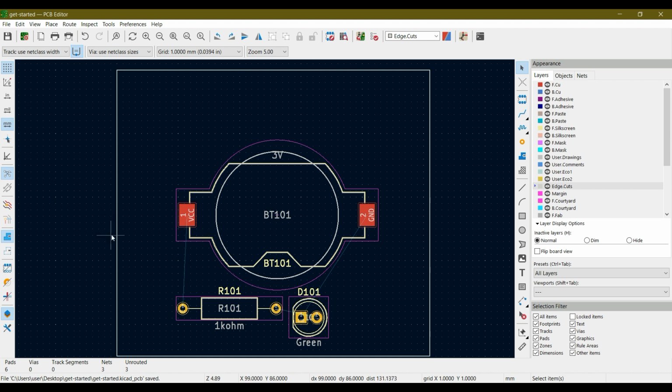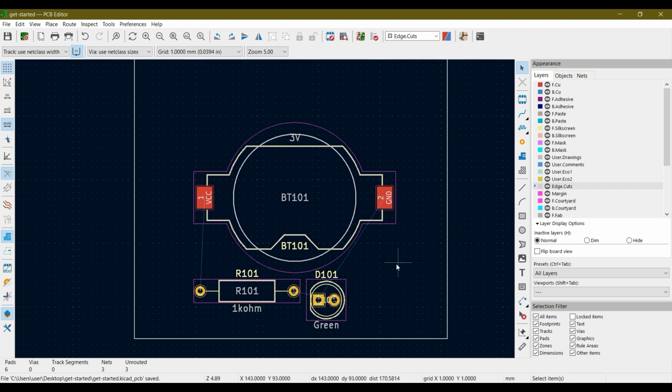Components should be positioned for ease of routing. If you don't have very strict restrictions on placement, like you don't have any connectors or something very sensitive to consider for its electrical parameters, then you can place your components for the ease of routing. Connected components should generally be close to one another and arranged to minimize routing complexity. You should arrange your components in such a way that you can easily draw your tracks.